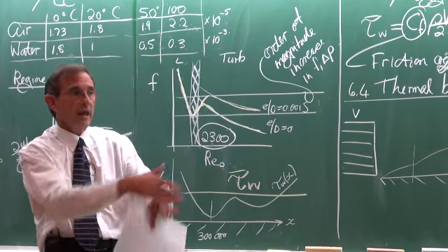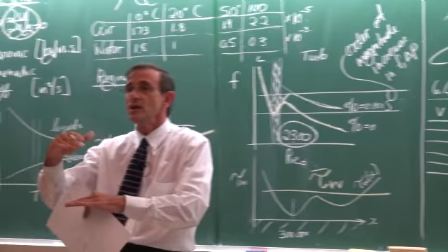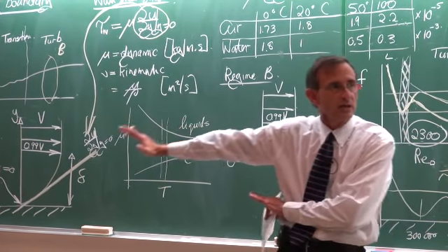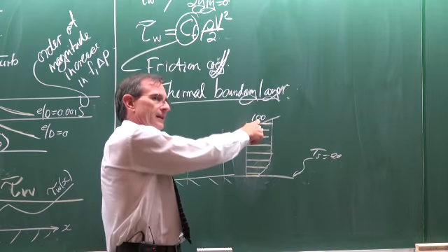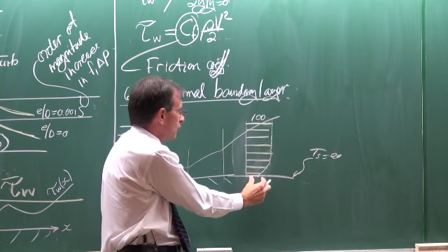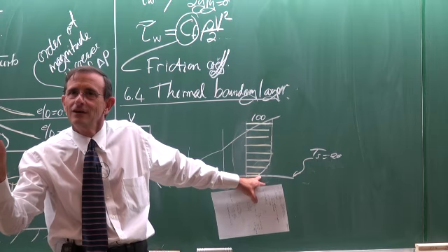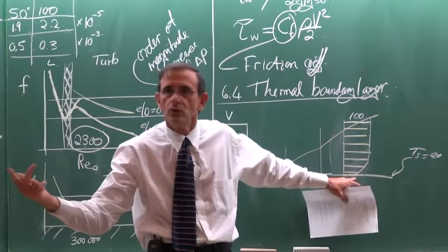Now, if we want to use the same concept of boundary layer thickness as with the velocity boundary layer, we cannot really say it is equal to 99% of that, because we have this value of 20 here. If the plate was at 0 degrees Celsius, then it would work.